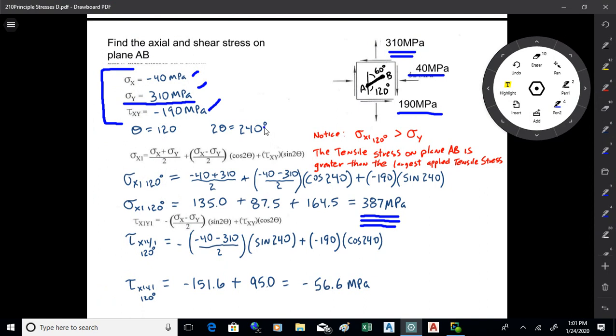We have ways of figuring that out depending on what it is you're designing. Once you have those, though, there can be stresses at different angles inside the object you're designing that are greater than the X and Y stresses. So you have to watch that, because when you design something, you generally design it for the largest stress. So we want to figure out how to find the largest stress that occurs in an object that we're going to design.